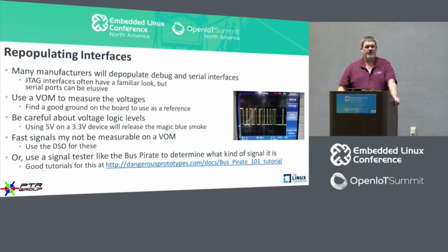Of course, a lot of manufacturers will depopulate the debug and the serial interfaces. So the JTAG interfaces in particular will be depopulated at a minimum. Sometimes you'll find the serial ports are depopulated as well. JTAG interfaces often have a pretty familiar look about them. So it'll be a 10-pin or a 14-pin or a 20-pin connector. Those kinds of things stick out on the board, and they're fairly easy to find.